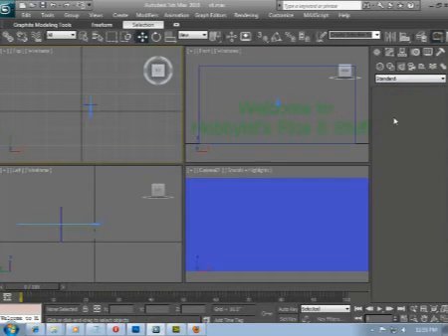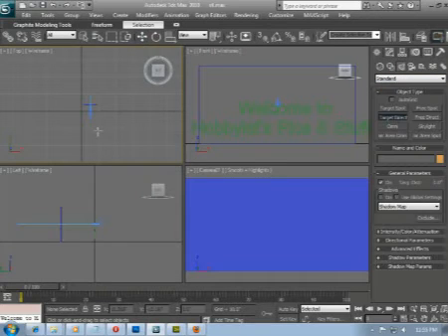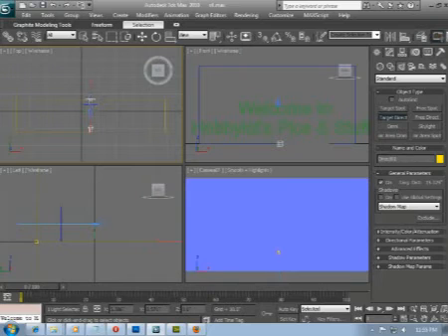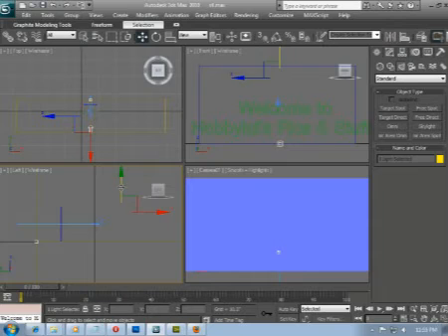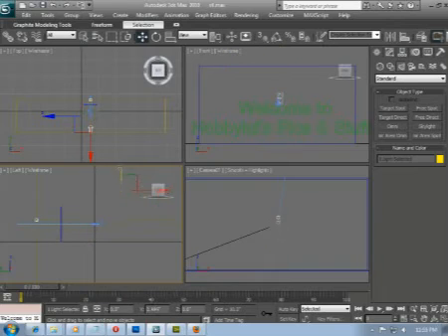And let's make it a target directional. Then we'll line up right behind the camera in the top view and drag the target just on the other side of our box. Let's right click in the left view and hit W to get ready to move. And if we can hit that line between the light and its target, we can use the up stick to get the light pointed right at the center.